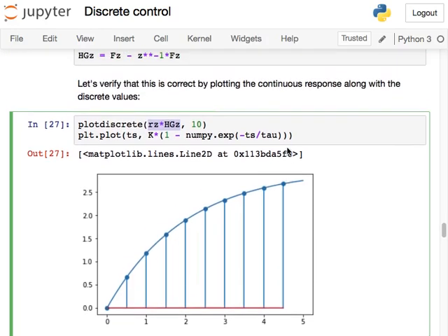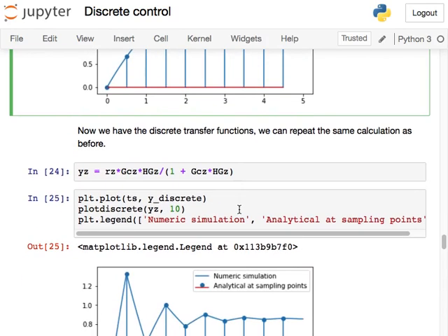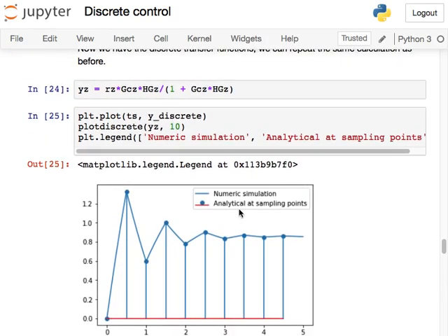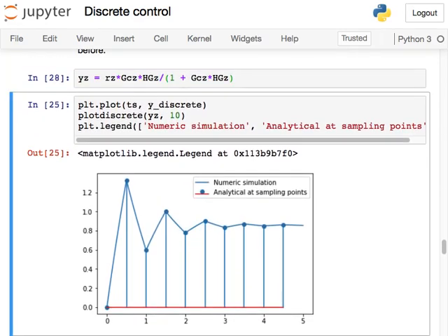More importantly, if we were to put repeated steps into this, in other words, if we would take a step and then do a step at time 2, for instance, we would correctly calculate the combined effect of those multiple steps. Okay, so now we can go through and actually get the closed loop transfer function. That's straightforward enough. A little bit later, I want you also to hear alarm bells ringing whenever you see closed loop transfer functions for discrete systems, because it's quite subtle when they exist.